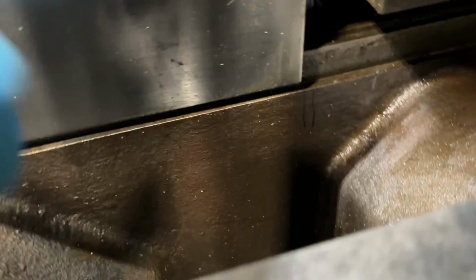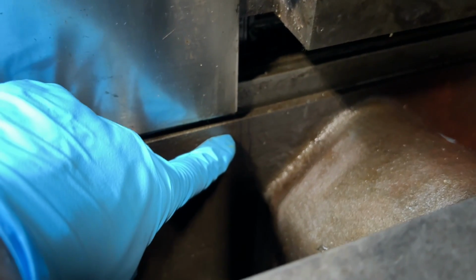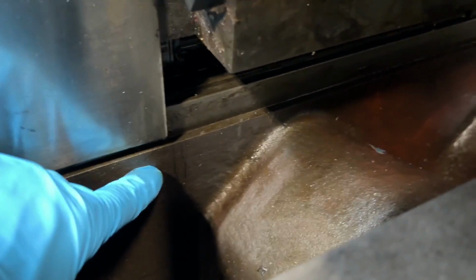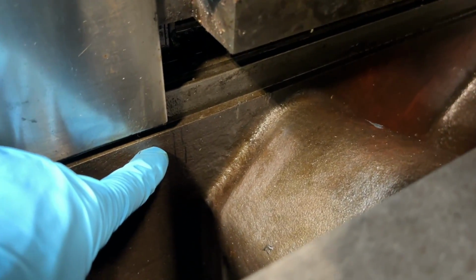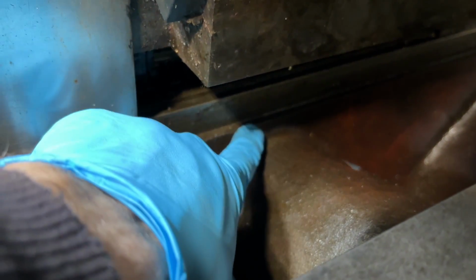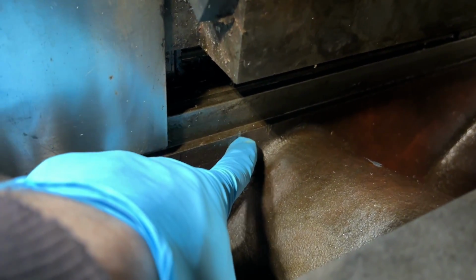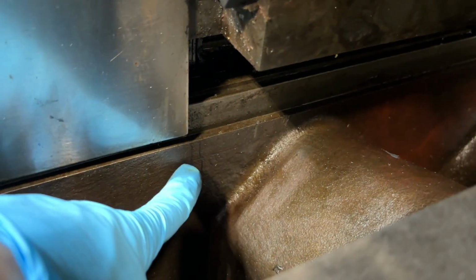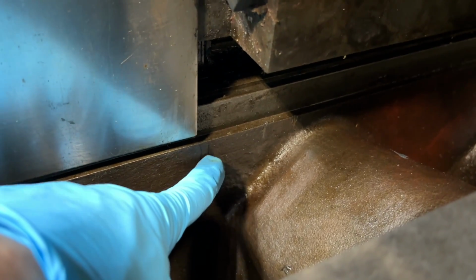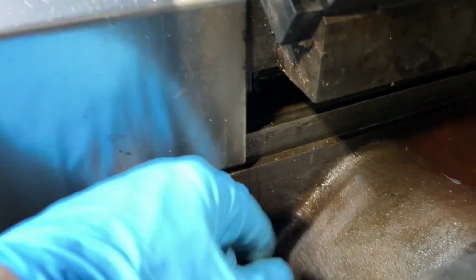So you see these lines? These were the lines that I wrote like a week ago when this problem started happening. So these lines I actually scribed in with a grinder. That's the hard stop, and that's about where I like to keep the soft limit. And these lines were when I was keeping track of this homing problem because it kept stopping here.